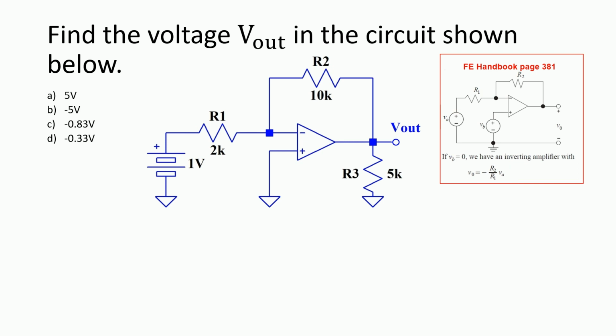So I'm going to derive this. I'm going to show you the way that I do it intuitively, and in this way I also never forget this stuff. Basically, I just start labeling stuff. This is my VN, and I start identifying my currents. There's my I1 and I2, and just by habit, I call this VA, and the other one VB. Because of the way amplifiers inherently operate, VA and VB are basically going to be the same. In real life, they are not, but for these equations and for all intents and purposes, they are.